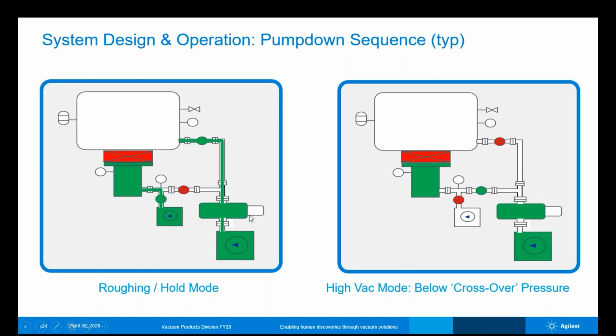And we're going to use our large diameter booster blower package here to be able to evacuate our chamber down to what we're calling the crossover pressure. When we hit our crossover pressure, we're going to open up this valve here. And we're going to allow the pumping pathway to happen along this way. So we're going to use our large capacity booster blower package as the backing pump for our diffusion pump at this point. So that's why when we talk about vapor jet or diffusion pumps, once we get into operation here, it's typically not a concern that we're going to exceed the foreline pressure because we've got such huge pumping capacity based on this booster connected to a single stage, typically rotary vane pump.